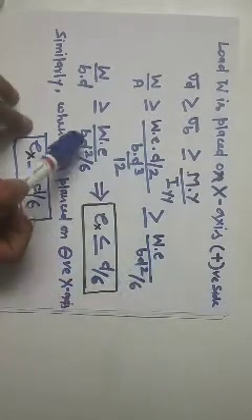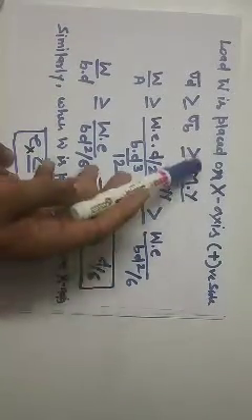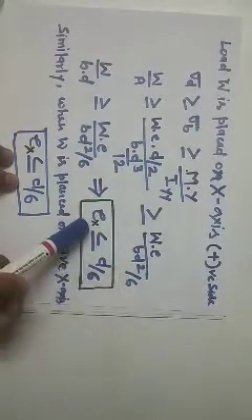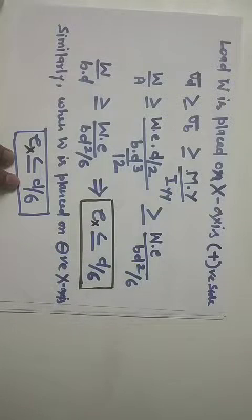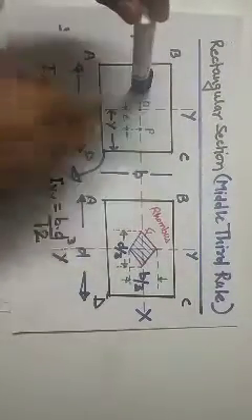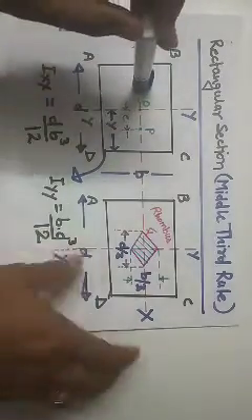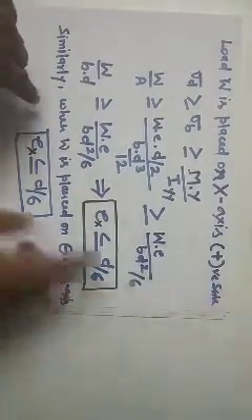Simplify this equation. When we simplify it, what do we find? e_x, because the load is on the x-axis and e is measured on the x-axis, so this is e_x. Then e_x is less than or equal to d by 6. And similarly, when W is placed on the negative x-axis, here on this side, at distance e, the same situation comes out, and e_x will be less than or equal to d by 6 for that calculation also.